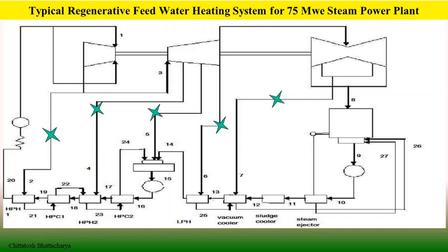Condensate is pumped by the condensate extraction pump, and after passing through the vacuum heater and low pressure heater is fed into the deaerator attached to the boiler feed tank, from where suction is taken for the boiler feed pump. The BFP discharge is passed through HP heater 2 and HP heater 1 successively before moving to the feed water control station for the boiler economizer inlet.